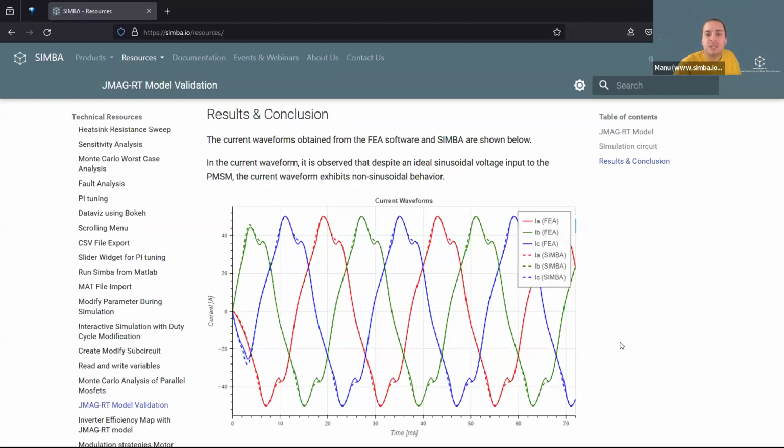Question from Philip. Did you calculate magnet loss if a PMSM was simulated? Those losses are highly dependent on the switching frequency and can increase the temperature in the rotor. The losses are not spatially resolved, right?